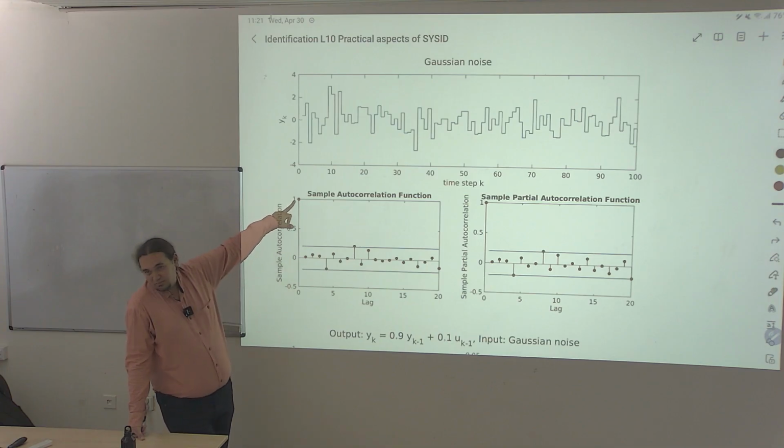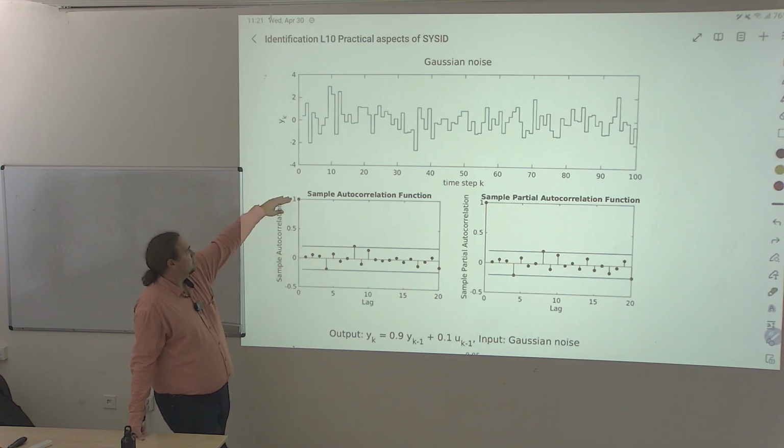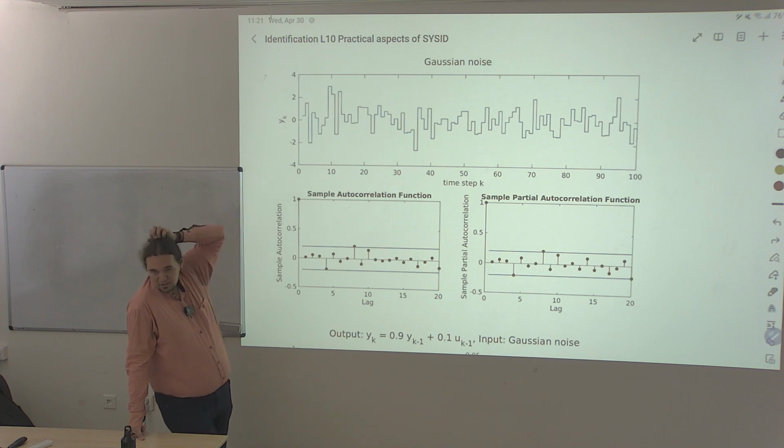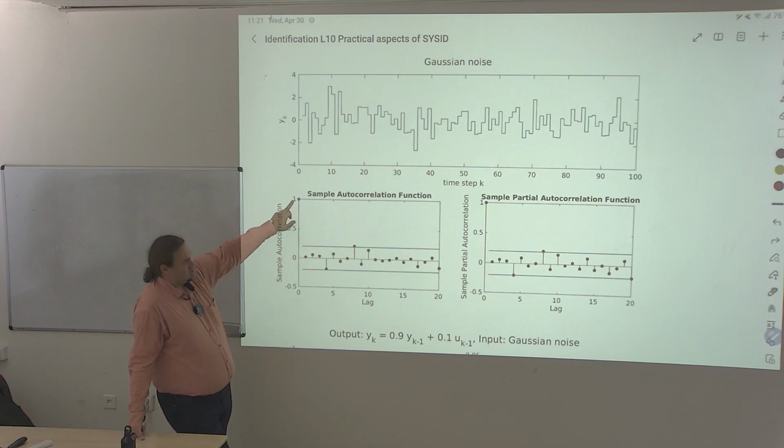We see that the signal has 100% correlation with itself, or that the signal either has a unit standard deviation or was normalized to the unit standard deviation, and this function will always do it. It will standardize the data. So what we can expect to see at the time 0 is the correlation with itself, the value of 1.